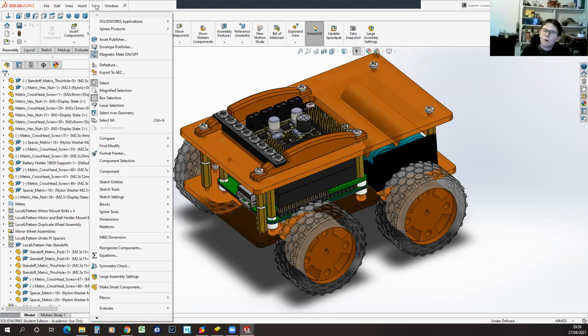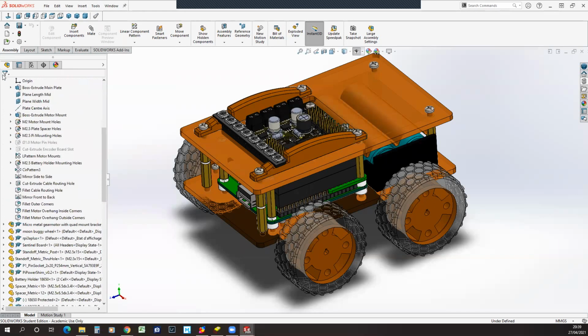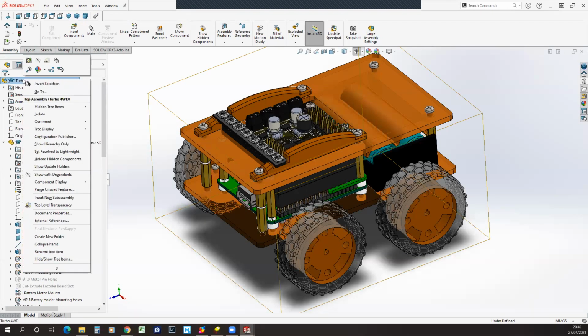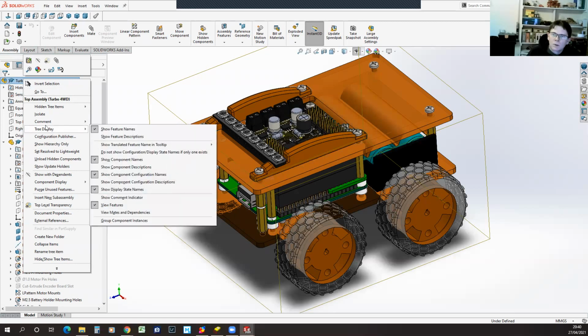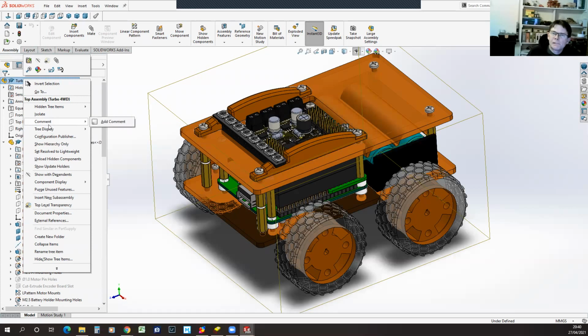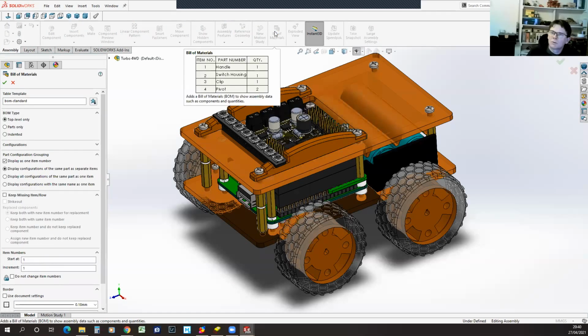I'm always up for a live demo. I can't remember where the bill of materials tool is. If anybody knows, shout out and we'll give it a go. Can you get it on the context menu for the parts tree if you go right to the top of your assembly? From there? Seeing it there. Ah, it's hiding on your menu bar now. Bill of materials. Just left of. Ah, yes, there we go. I knew it was somewhere.